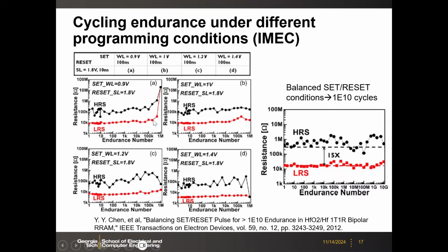So you see at the end of the lifetime of the device, the resistance all shifts up, and there's no switching here. The device is dead. This is after 1 million, 1e6 cycles. This is because the reset is strong, so the device tends to go to higher resistance, and will eventually fail, or some people call it stuck at HRS, the high resistance state.